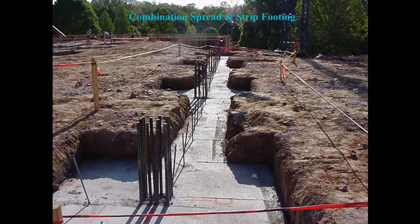Here we see a combination of spread and strip footing, where we have probably what are going to be some column locations along the building here, so they've widened out their footings for the columns, and also put in a strip footing connecting these that they're going to pour their foundation wall on top of.